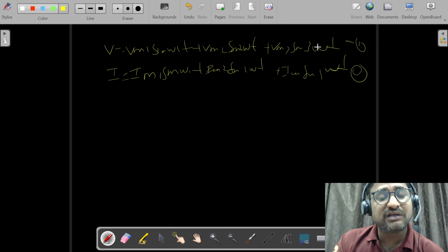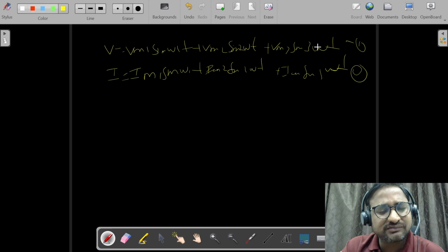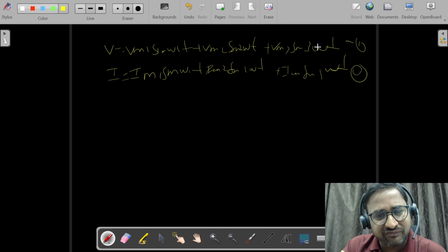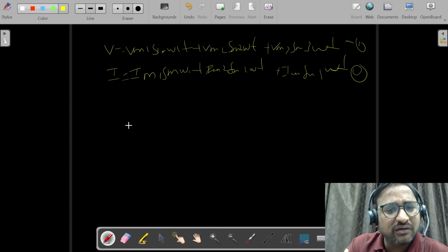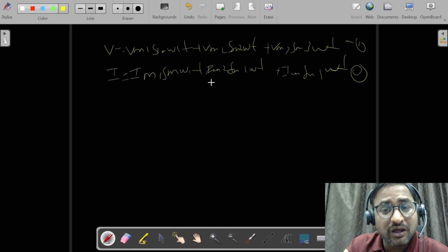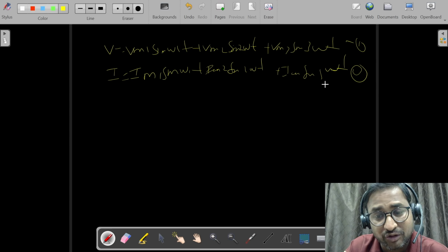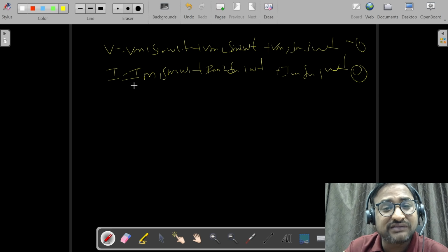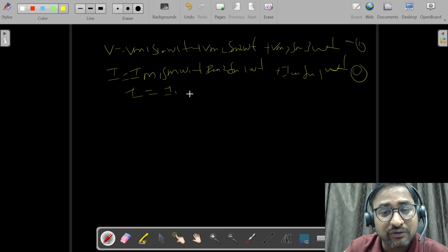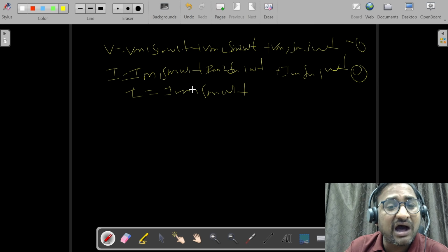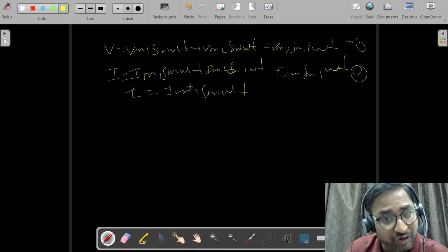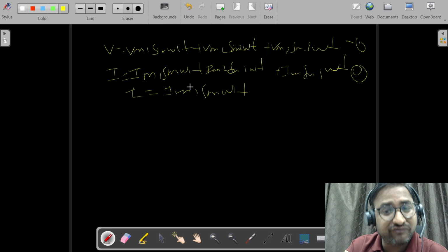So now I am going to explain what happens if harmonics are there in the system. With this equation only I'll explain. Check the second equation: I is equal to Im1 sin omega 1t, Im2 sin 2 omega t, Im3 sin 3 omega t. In this way, my current component is increasing. My fundamental current is nothing but I is equal to Im1 sin omega 1t. This is the only required current for me. But due to the harmonics, extra frequencies are getting into the system, like Im2 sin 2 omega t, Im3 sin 3 omega t, Im4 sin 4 omega t, Im5 sin 5 omega t.